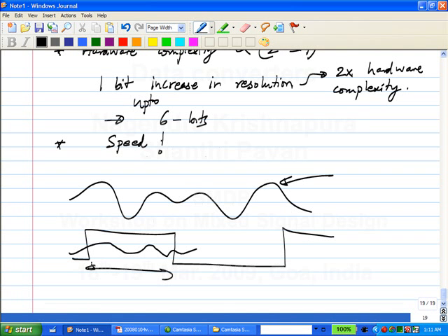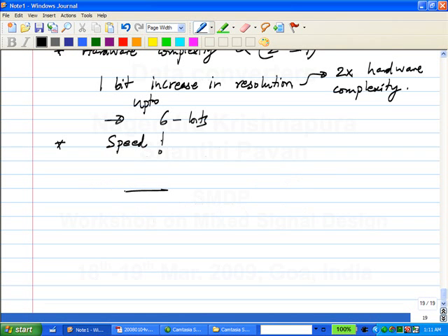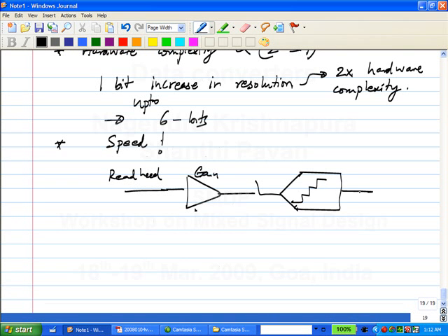So what happens in a disk platter, therefore, is that there is this analog signal coming from the read head. This is very small, so this is amplified, right? And then from this you have to digitize it, okay? Alright, which means sampling and quantization, right? So I'm going to explicitly put the sampler and this is the quantizer. This goes into DSP where they look at these samples and then try to unravel what bit sequence was written onto the drive.